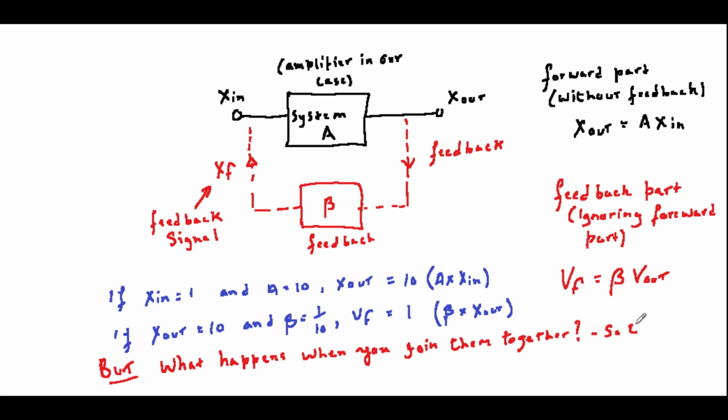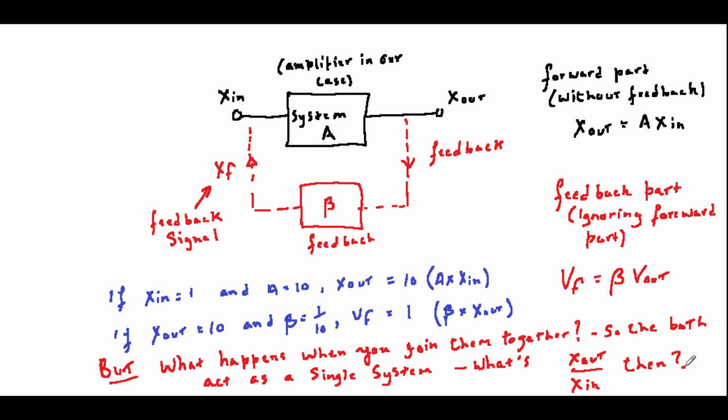One problem that we will come across in circuits is that negative feedback can sometimes turn into positive feedback and cause a device to become unstable. It does this because of unwanted effects, particularly parasitic components. These can cause the feedback or the forward signal to become unexpectedly phase shifted. Unwanted feedback can also occur if a signal gets into the power supply lines, and this is why decoupling components are so important.